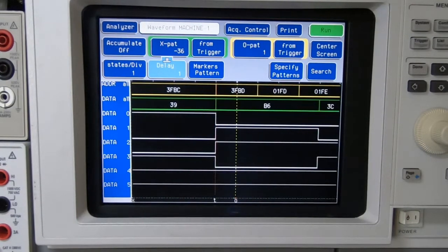and the first thing to note here, and this is something that is a real trap if you're not careful and you don't understand fully how to use these machines, is although we've captured some data here with the analyzer, in other words we've triggered the trigger event that we've set, it's incorrect. I've pressed the key in this case to capture this, and it's consistent, it will capture this every time when you press a key. But as it turns out, the keys are not handled by the interrupt controller.